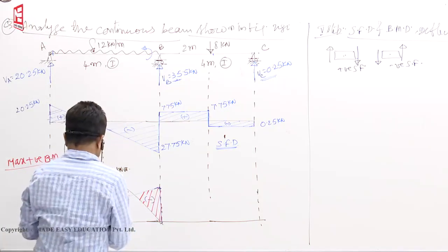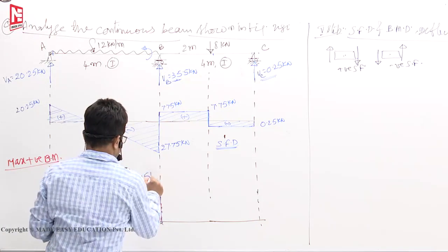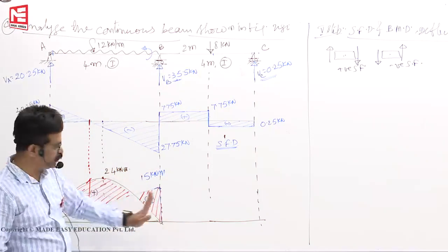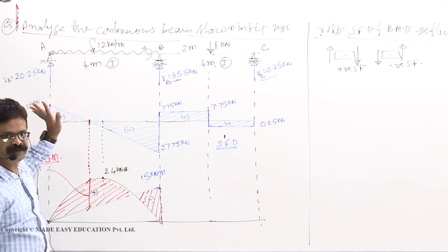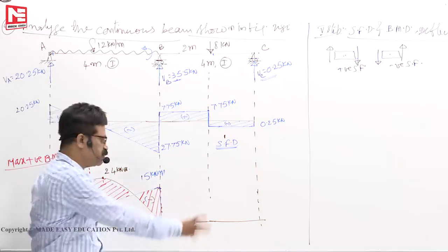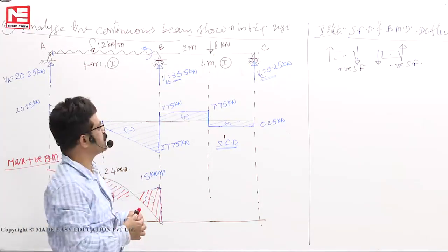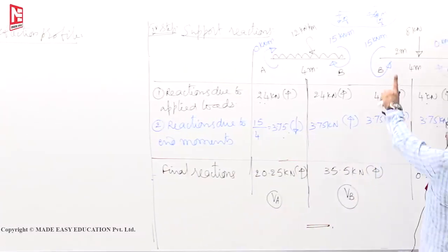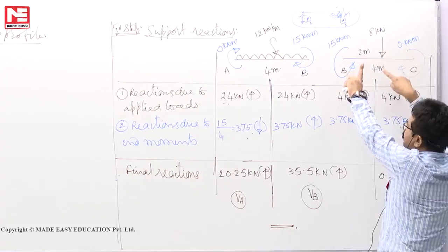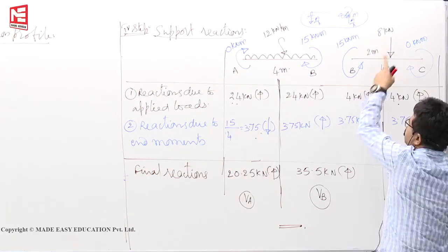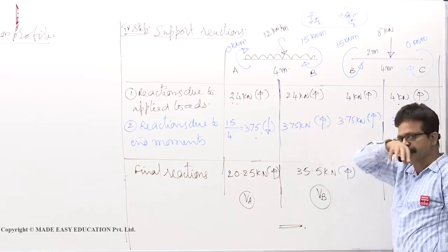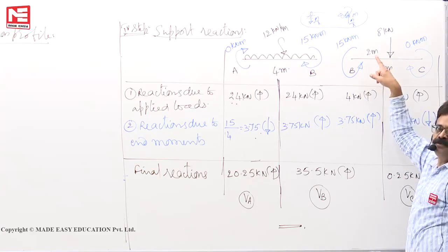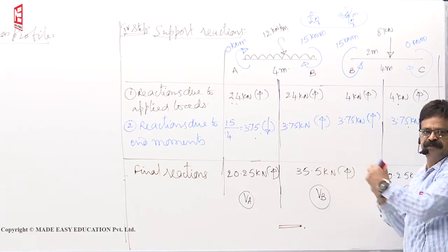Next, this is 15. So bending moment diagram due to UDL, due to end moments you have drawn for the span BA. So it's complete bending moment diagram. Now independent of this one, you can draw another bending moment diagram here for the span BC. Now come to this point. If you take the span BC, it is now again like a simply supported beam subjected to central point load. Simply supported beam subjected to end moment. We know from strength of materials how to draw each bending moment diagram. So due to point load, triangle, another triangle due to 15, superimpose them, net bending moment you will get.